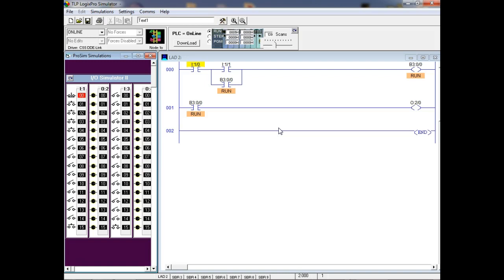Selector switches you'll run into every once in a while, where we can set up what we call a run jog circuit. But anytime it says a master switch, this is the circuit I want right here. Because you're not going to run into a circuit that's got a master switch. You're going to have this guy right here. So now I just have to go over and press a button to start it and press another button to stop it. You understand?